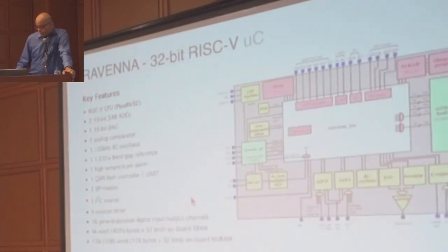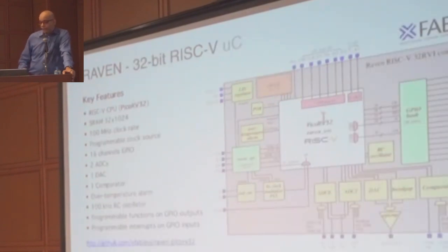The most important part of these chips is that they're a mix of open source and closed source. So the RISC-V core here is open source. The rest of the chip, the IP, especially the yellow-greenish parts, these are closed. The chip itself is open source, so the netlist of this chip is open source and available on GitHub. When you put it together and push it with eFabless, eFabless puts the hidden guts in and sends it to manufacture.